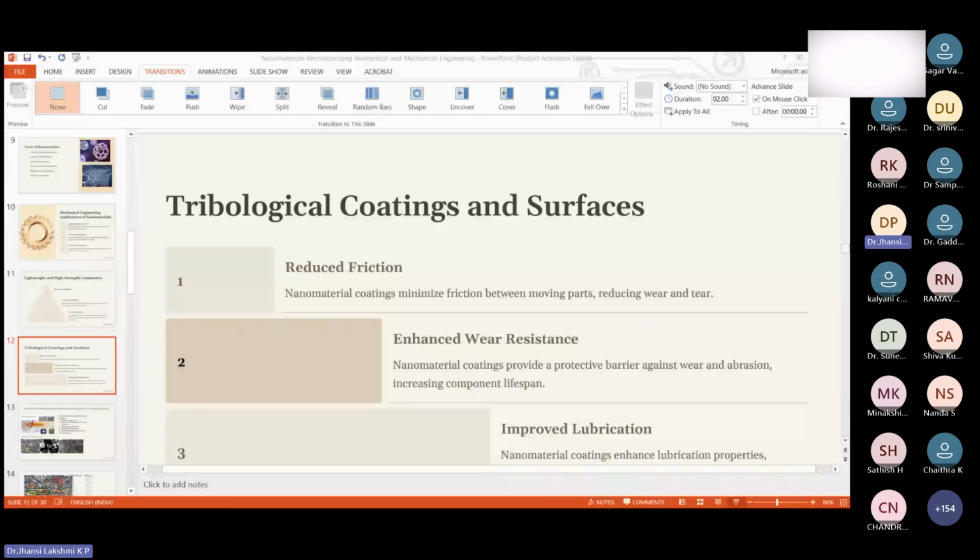A few partially melted particles and unmelted particles are seen, and even cenosphere is seen. When XRD and EDS of the material are taken, it is observed that all the elements in the feedstock powder are there in the coating. After that, the coating thickness is checked.